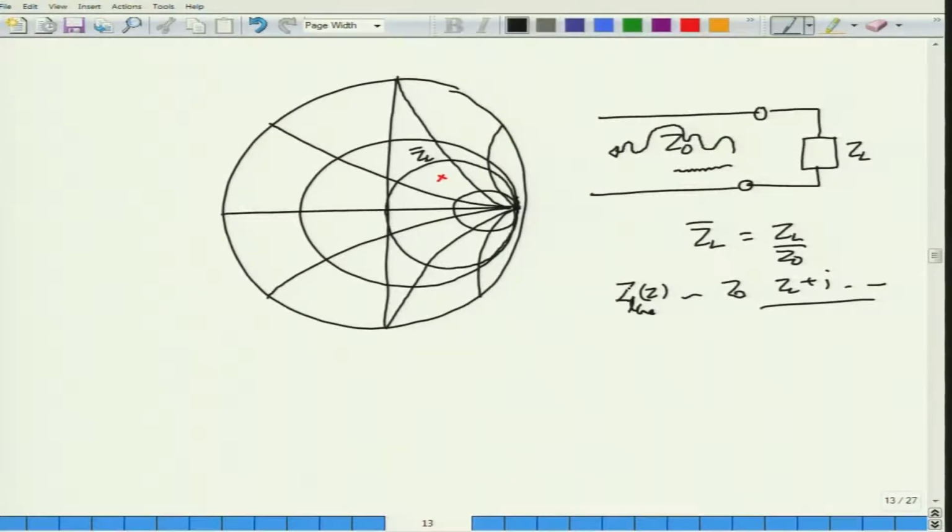While it continuously changes, at some particular point the impedance might be such that you would hit 1 plus jx. When you hit 1 plus jx, you can stop, cut this transmission line, and replace this portion on the left-hand side by a transmission line terminated with something that gives a reactance of minus jx, such that when you move past that plane, the total impedance seen here will be equal to 1.